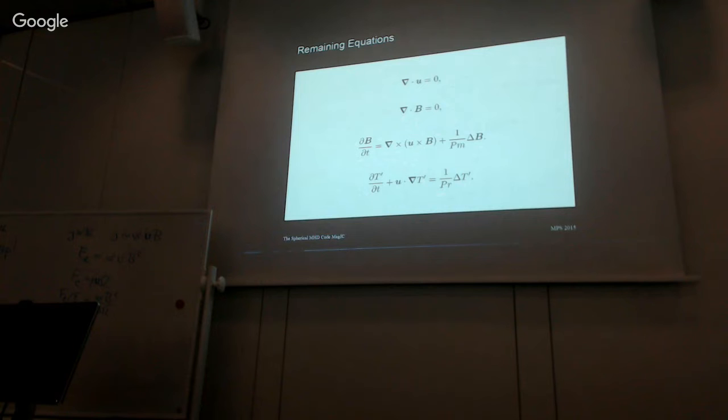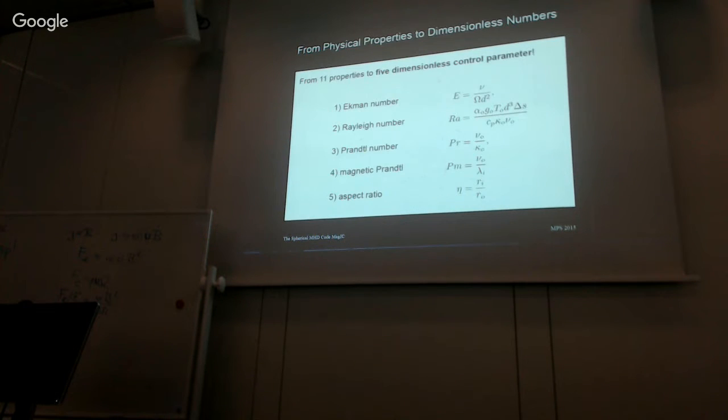So these 4 plus the Navier-Stokes equation are the equations that we saw in the Boussinesq approximation. The code actually allows for an anelastic approximation, so you will have some additional terms which deal with the gradient in the background density state, but that would be too much of a complication now.